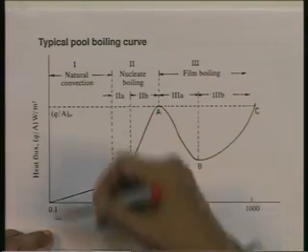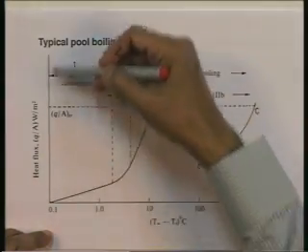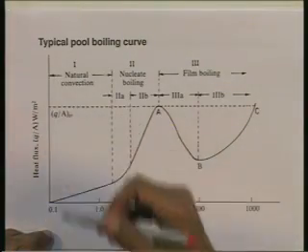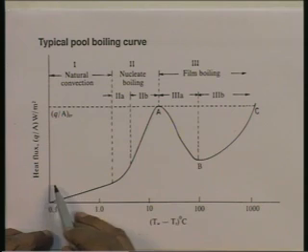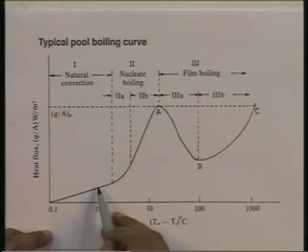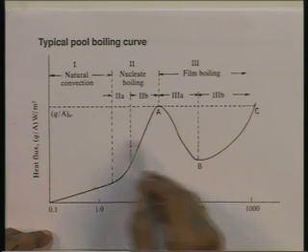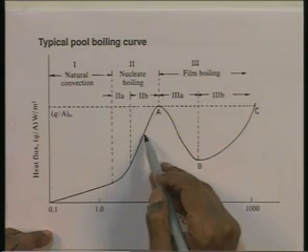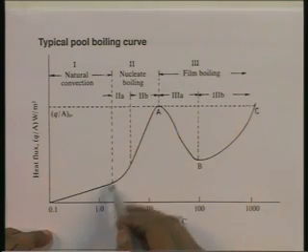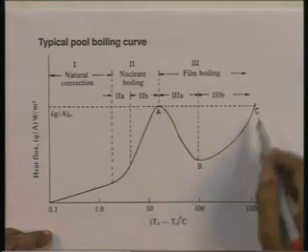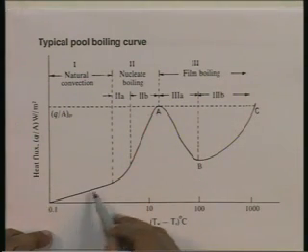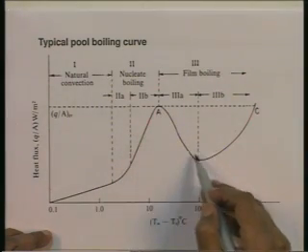Then on the y axis, we have the values of heat flux that we are supplying for maintaining these values. So, at each steady state, at T W minus T S equal to 1, what is the Q by A? Measure that and put down that value. Next, go to say 10, find a value of Q by A, you get another experimental point. So, you generate a series of experimental points and then draw the curve, and the curve which you get is something like this. It is a very interesting shape.